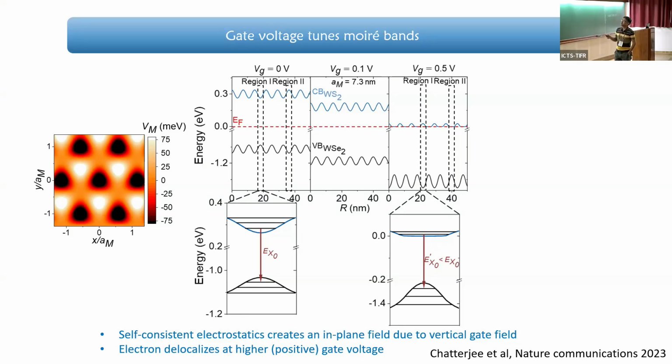But the moment this guy comes close to the Fermi level, it will start introducing carriers. And the moment it starts introducing carriers, it will have this screening effect. If you look at it carefully, this edge will come closer to the Fermi level earlier than this part. What it means is that this portion will be screened more compared to the other portion. So in effect, if you introduce more carriers in the system, your fluctuation is going to go down, which is obvious.